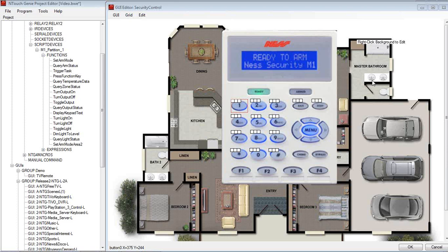If I right mouse click on those, I want to go to an external JavaScript, and in here it's telling us what function we want to do and what data we need to put in here. So let's get rid of all that, the function is going to be a key press, and in this case it's going to be digit 1. We hit OK. I need to do this for each of the buttons. I can hit Control C and Control V, make it easier.